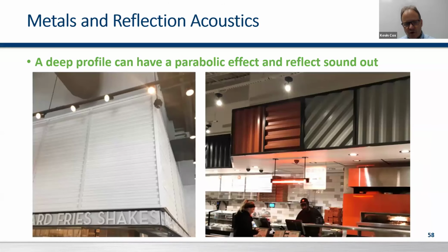So not only can we absorb sound through perforations, but we can also use it as a parabolic reflector, or reflect sound back into a space. Usually the deeper the profile, the more it's going to grab and focus the sound. Both of these are in malls. It's a Shake Shack on the left and a Blaze Pizza on the right. Nothing attracts a crowd like a crowd. So we can use it as a reflector. Some of these spaces, you'll notice neither of those have acoustical ceilings, are designed to be a little louder so that we can bring some attention to the space. And during lunchtime, hey, maybe it's time to get a burger or get a slice of pie.